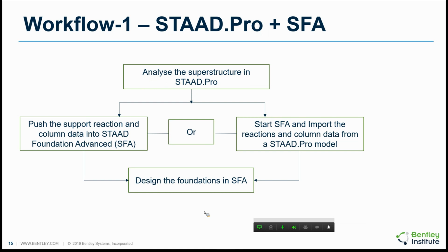Alternatively, you can close down StatPro, go home, come back tomorrow, start SFA, and import the reactions from the results of the StatPro analysis. And the results would include the support reactions and the column data from a StatPro model. And once that information comes into Stat Foundation, you then design the foundations in SFA.